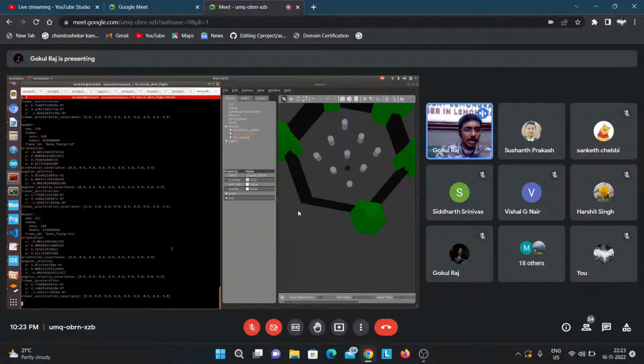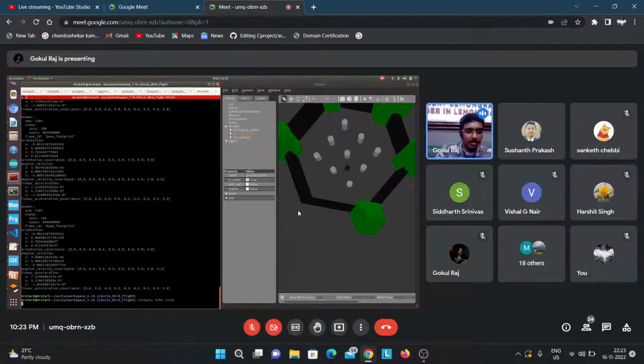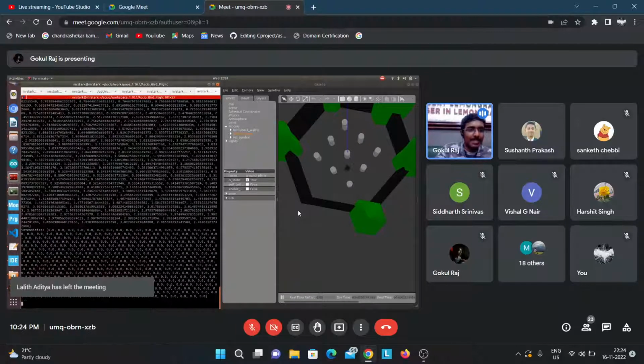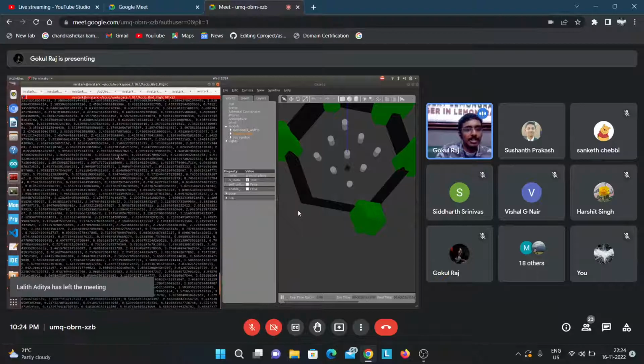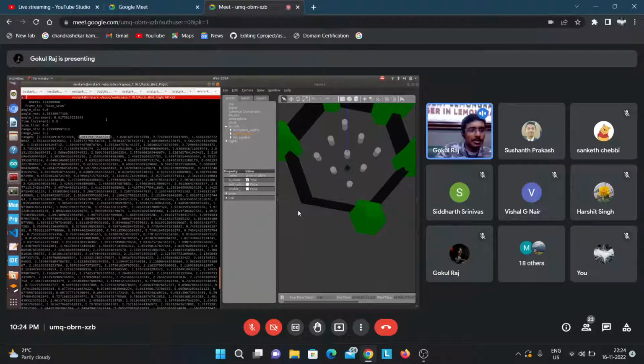So you can see the IMU data published from your Turtlebot over here. Your Turtlebot has a LiDAR, which is publishing in a topic called scan. LiDAR is basically nothing but an ultrasonic sensor, but in 360 degrees. This particular LiDAR covers 360 degrees with this particular range. This is at 0th degree, this is first degree, so it has 360 points. If you want the distance at the 90th degree, you can subscribe to this message and see the 90th data of this array. That will give you the distance of the object at an exact straight angle to the robot.